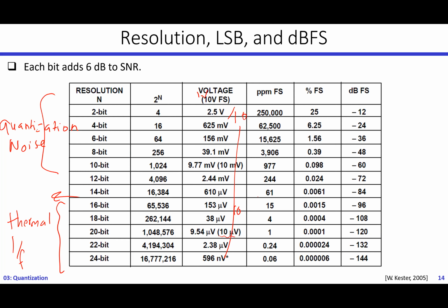Now, therefore, the thermal noise becomes more dominant because, let's assume, it has a constant value, while your quantization noise significantly drops with increasing your resolution. And therefore, this is the dominance that we are talking about here. So that's a part when you will be designing: you will need to know which is more dominating and use the proper techniques to reduce these noises.